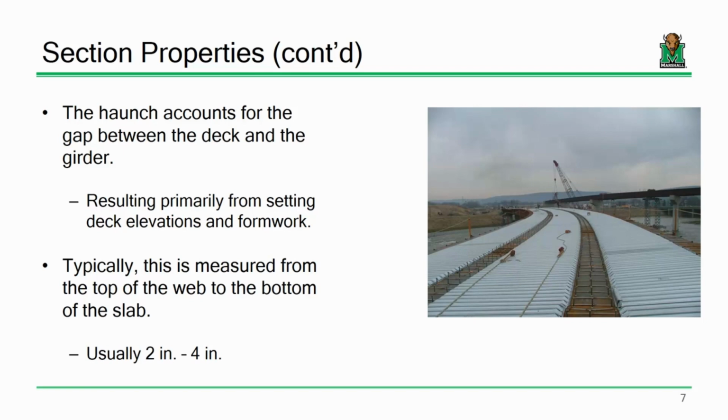So you can get failure limits that are a lot lower than you would think. Steel tends to have a yield stress, or at least a pretty common grade for what we use in bridge applications, of 50 KSI, so 50,000 pounds per square inch. But we can have fatigue categories that can fail at 6 KSI or 8 KSI or what have you.